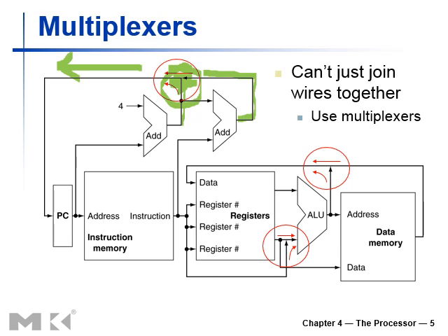If we've got two options here, we need a selection mechanism that selects when we have to give this PC plus 4 to the program counter, or when we have to add some other data into the program counter. So these are the problematic nodes here. We have to resolve that, and we have to use multiplexers. Those are the devices that select among your choices depending upon the selection criteria which you've provided. So we use multiplexers to select our data in order to avoid this issue.